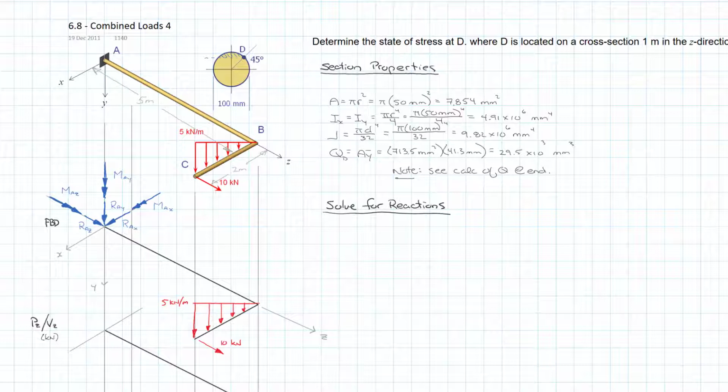So forces in the X direction, the Y direction, and the Z direction, all at A, as well as 3 potential moments, with moments about X, moments about Y, and moments about Z. And so I'm going to calculate each of those, and then from that, we're going to draw the graph or the diagram for the forces, the shear forces, and the moments that are appropriate to what we're doing.